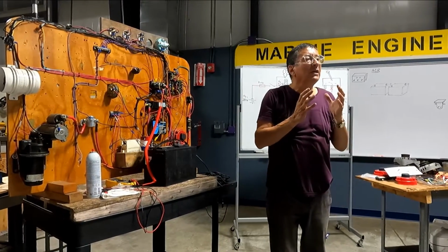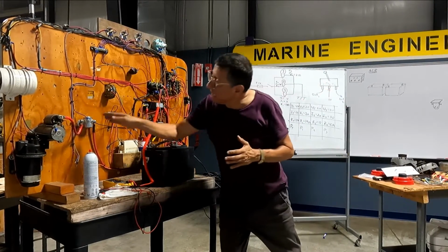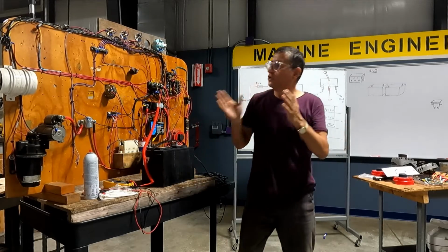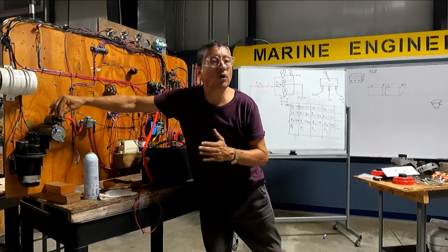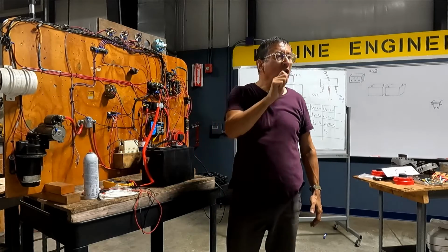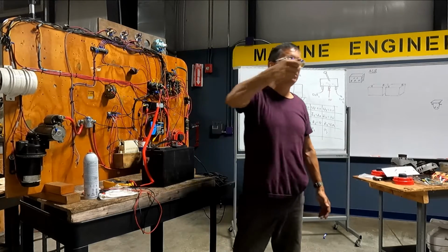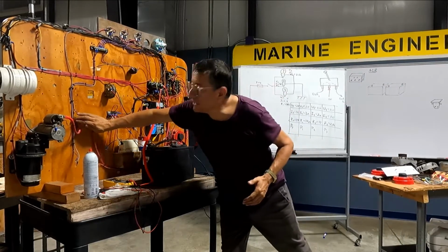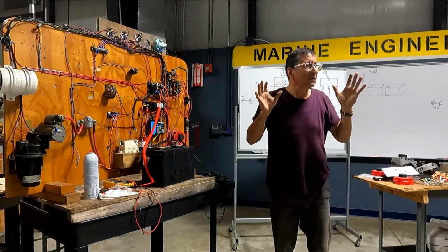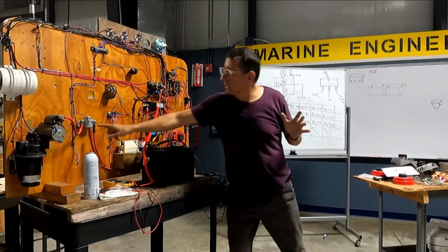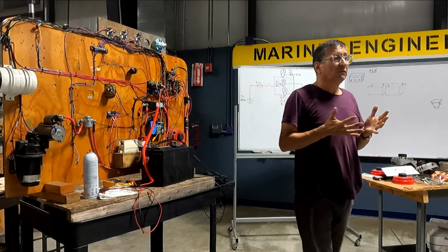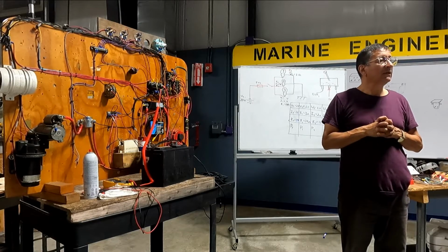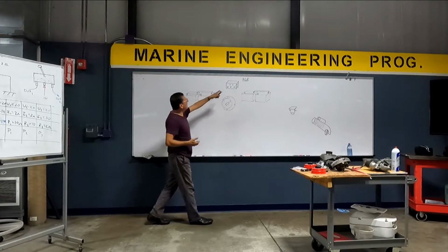For that reason, in marine applications, you install that relay in between this point and the battery to keep this point with no power. Only power in the moment that you start. This is for safety. Yes, in your car you don't have this. Some cars do use that relay. It's good for safety. Good, my friends? It's clear?